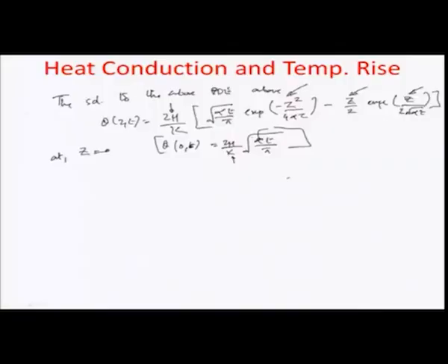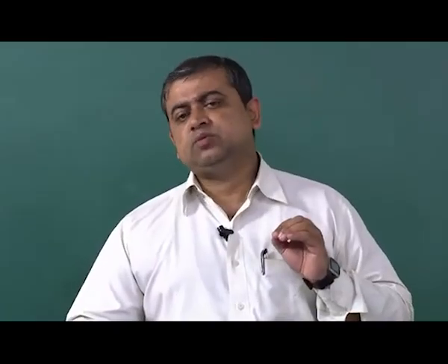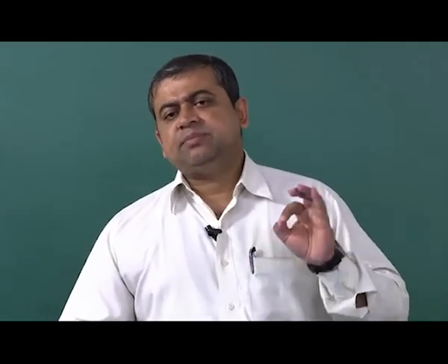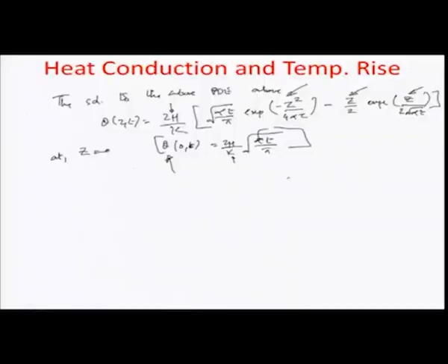The units are watts per millimeter square. So, why does melting happen in laser machining, or how does melting happen? The surface of the workpiece, which is being hit by the incident laser, reaches the melting point of the material. So, this theta m here is nothing but the melting point or the melting temperature of the workpiece or work material.